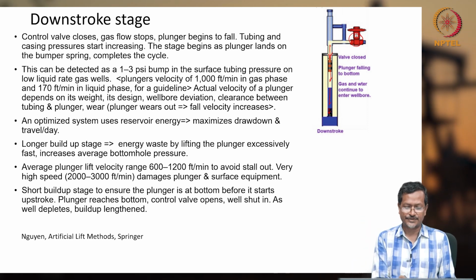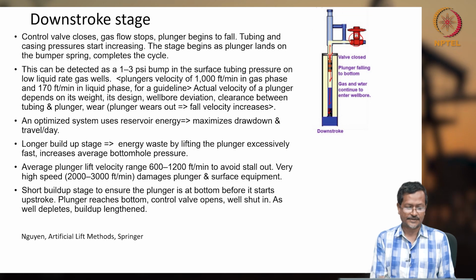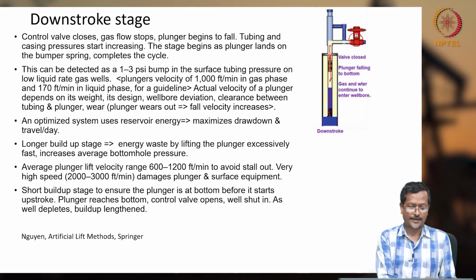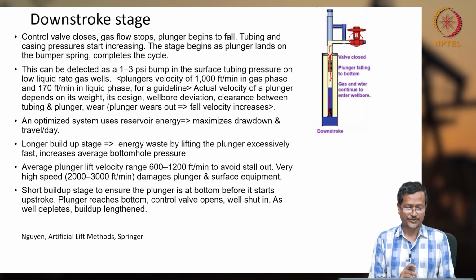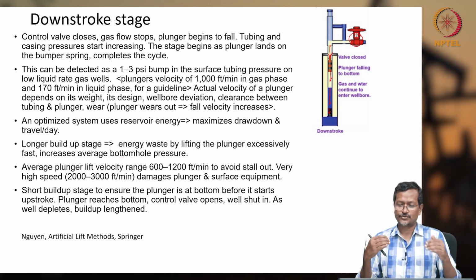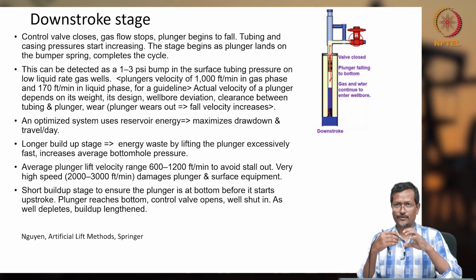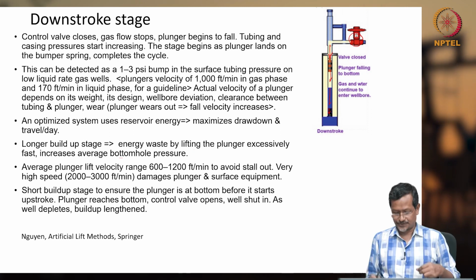Longer build up stage, energy waste by lifting the plunger excessively fast, increases average bottom hole pressure. So, you have to optimize there whether you want a longer stage or a shorter stage.